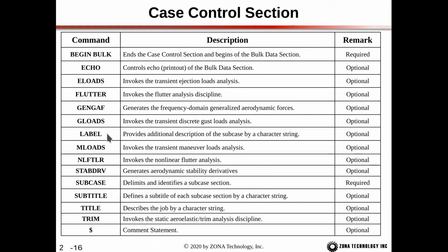And then we have more non-subcase cards. So label provides an additional description of the subcase by a character string. Subcase delimits and identifies a subcase section. Subtitle defines the subtitle for each subcase, and then title gives an overall job description.